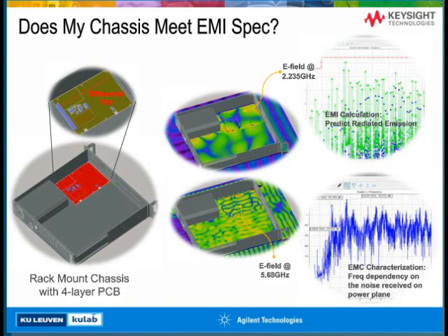The green color is the emission level based on the common mode injection to this differential pair with the slot on the ground plane. As you can see, the emission level now is close to the EMI limits, which will be the main source of the problem.